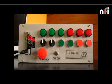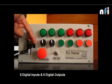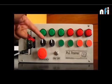This is our PLC trainer. You can see on the screen, this is the PLC we have of the company Delta. It's written DVP14SS. Now this 14SS means it contains a total of 14 terminals. 8 are the inputs and 6 are the outputs. And these inputs and outputs are internally connected to these output indicators, and these are the inputs.